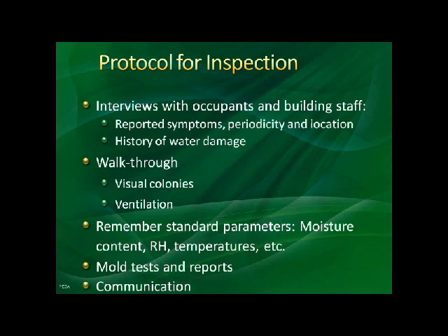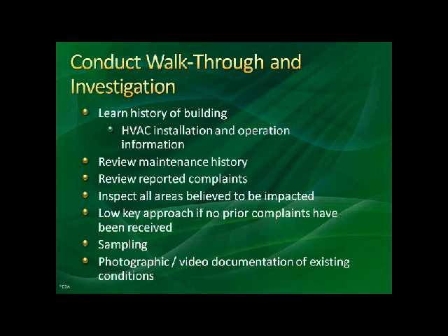When you do your inspection, you want to get the symptoms, history of any water damage, walkthroughs, and look for visual colonies of mold, and whether there is proper ventilation. We teach all of this through the courses. When you conduct the initial walkthrough, and this could be commercial, you'll want to get a maintenance history. Any sampling that you're going to do, you're going to notate. You're going to take photographs and or videos.